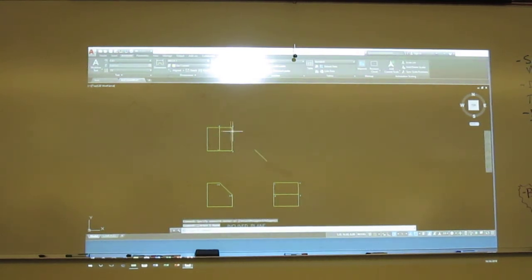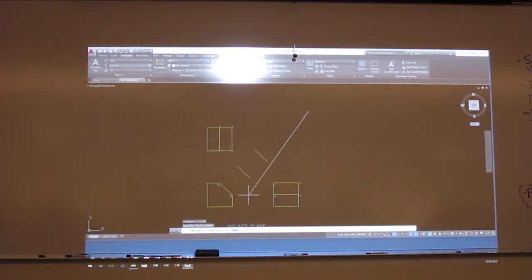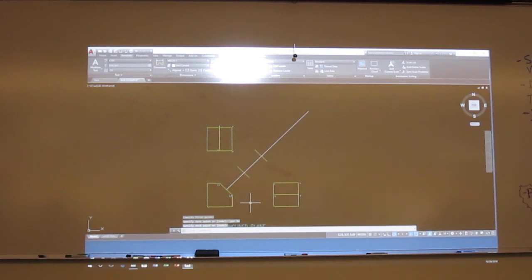So there it is. That's the same as 3, 4 right up here. So I'm going to do offset, and I'm just going to measure from there to there and throw that distance out. Now on this one, once we already know our endpoints, so I could just draw those right in. But just to show you that it works, I'll again get out here, and force my perpendicular snap. Okay. So there it is. Then move this guy to an edge and copy it to the other.